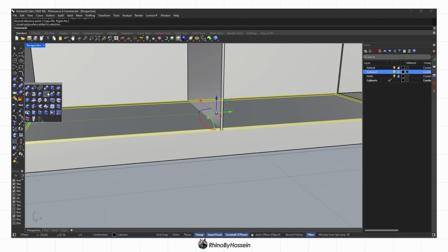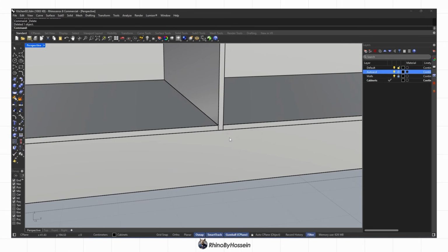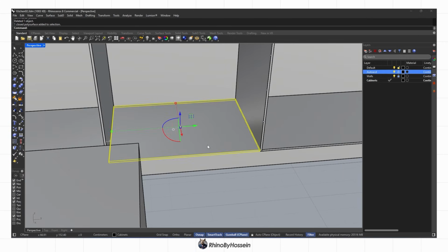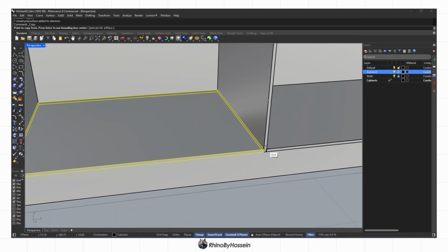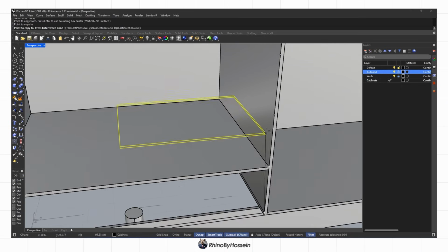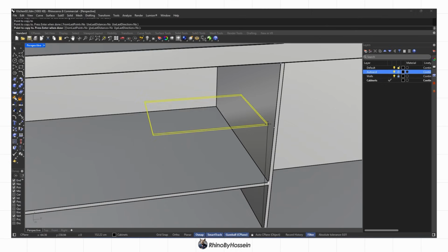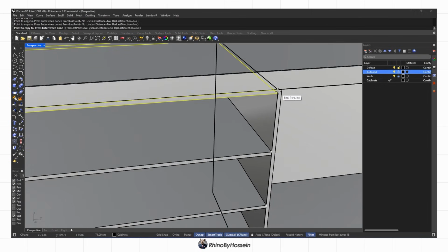At this stage, we make sure that the vertical members extend down to the cabinet base, and the horizontal panels are pushed in about 1 centimetre to create a recessed edge, giving a more realistic feel. This process is basically the same for all drawer cabinets.